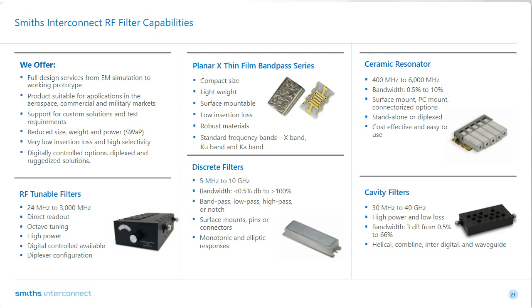Through hole vias are laser cut or drilled. What about surface metallization impact? I can answer that one. Typically, you laser drill. So you use a laser to pre-cut the holes before metallization. And there are processes like bead blasting, for example, that make sure that any kerf or anything that's generated during the laser processing is removed. So it forms a very, very solid, very good adhesion.